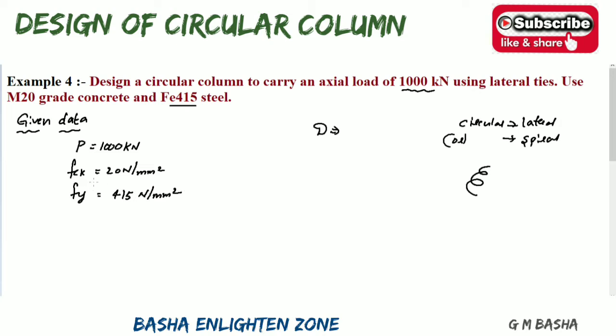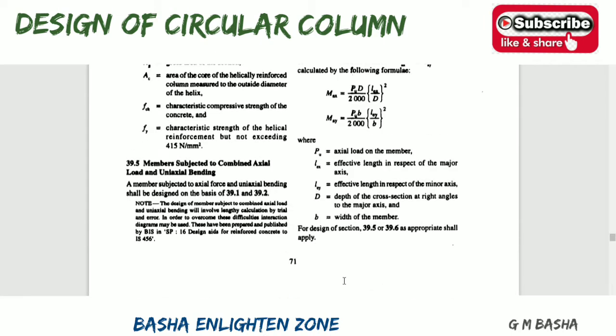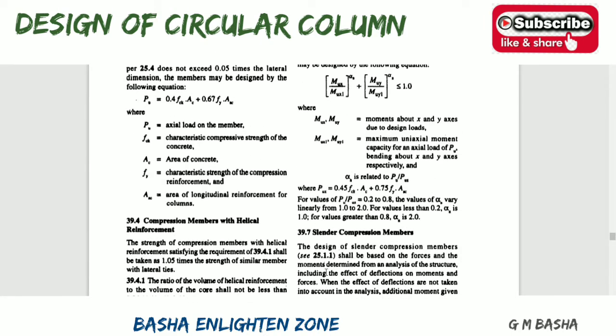For solving this problem, I already told you one formula which is given in our Indian Standard 456 book. See here, short axially loaded members in compression. The page number is 71 in IS 456. We already solved one or two problems in the previous lectures based on this formula. Please take down the same formula: Pu equal to 0.4 fck Ac plus 0.67 fy Asc.